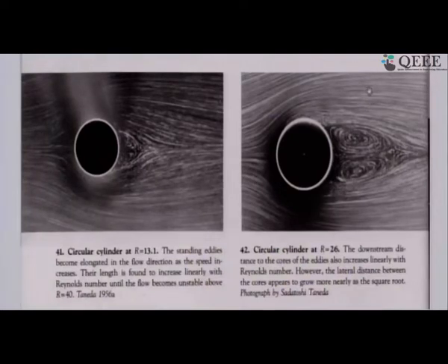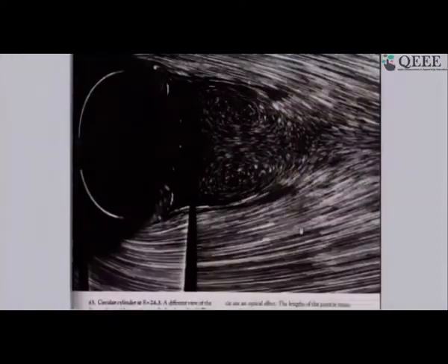The fluid is not mixing with one another in this direction, and that tells us that the flow in all these cases is laminar. So you got the Reynolds number 26 and you still have laminar flow. Now, this is a picture at Reynolds number of 24. What I'm showing you is experiments. So you actually make an experiment, take photos, and see how much we are able to learn by looking at the photograph of a flow.